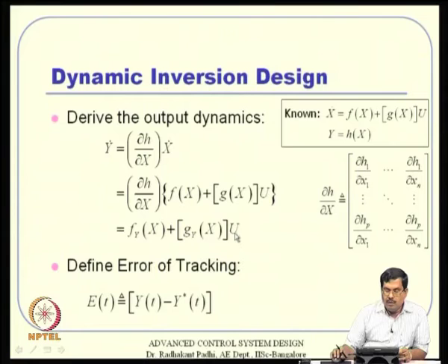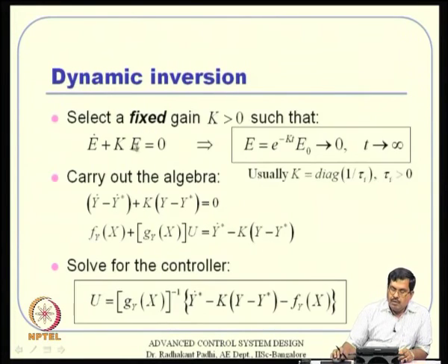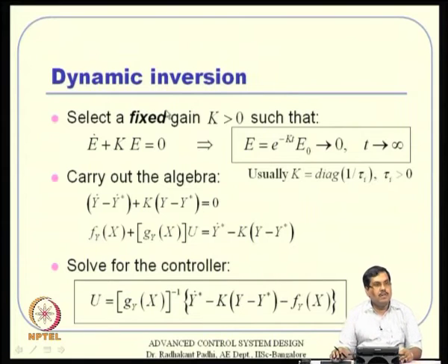control design u in such a way that E of t should always see some sort of stable first order, time invariant linear dynamics. So, how do you do that? We will need to enforce this dynamics by some gain selection k, which will operate here. Most likely we will see some sort of a fixed gain k, that is what most of the time we will be able to operate.